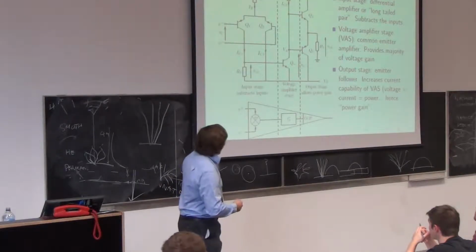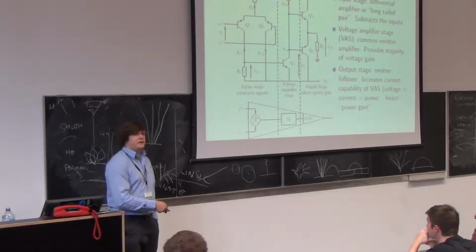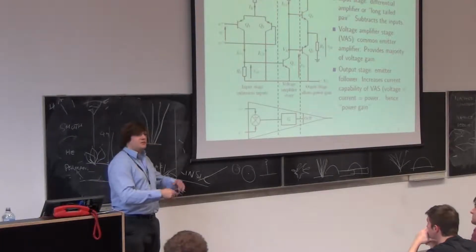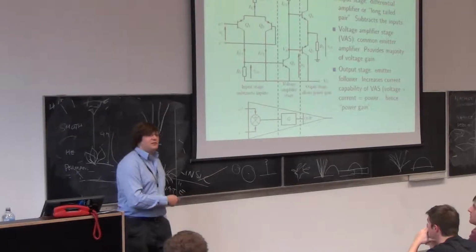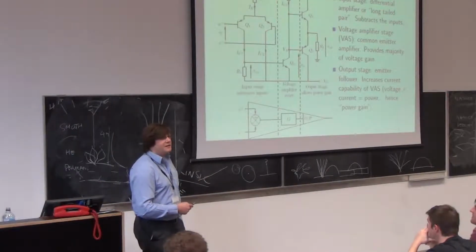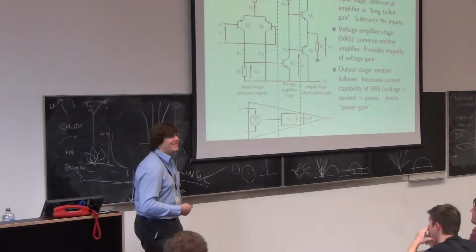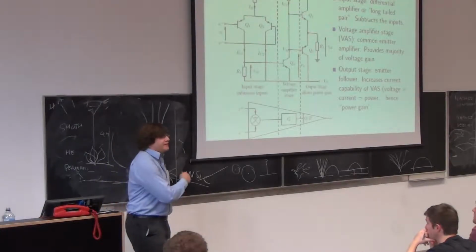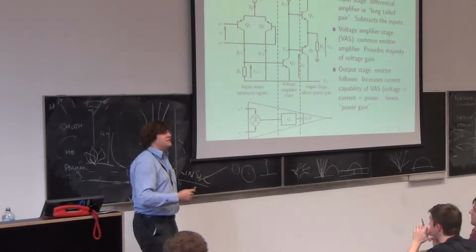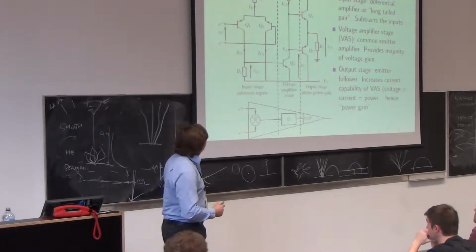Yeah? So, this is the skill of the engineer: to sit at the circuit and go, what do I know? Let's apply Ohm's law. 0.7 here, here and here. Bang. Of course, if you apply the 0.7 in the wrong place, or you say I is R upon V, then you will come up with a load of nonsense, and it will sound just as good as if it's right. So it's something that needs practice.